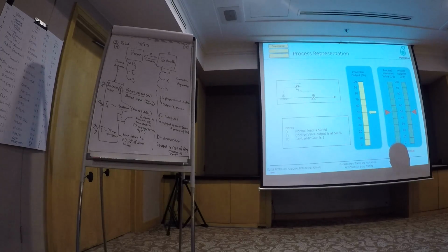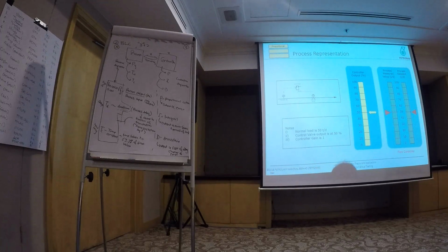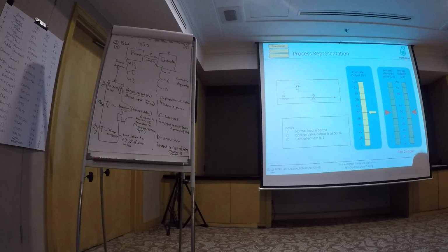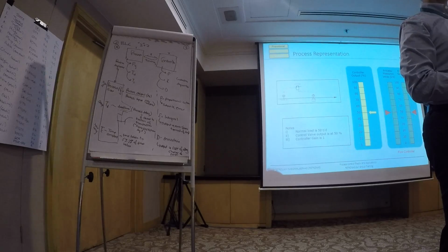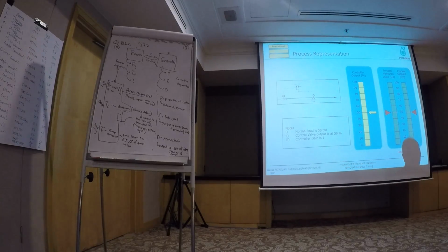Which is an issue. Where's the issue here? The issue is if you transition from a Yokogawa system to a Foxboro system. Why? You want to put 2 minutes, okay, I will use 120 seconds. Then I go to a Foxboro system and I type 120. Now, if you think about it, that's not an issue. It's okay because 120 minutes of integral is extremely slow. What if you put 2 minutes in Foxboro, and now you go to Yokogawa and type 2? It became 2 seconds. And your loop suddenly jumps. So you have to be aware of the units when you're working on the DCS.